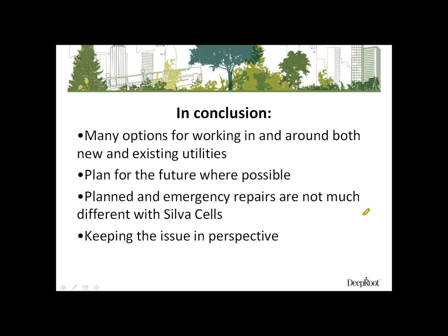If you think of it as a modular block retaining wall, if you have to make a repair underneath that, you have to start at a big V at the top and work your way down more narrow until you get to how wide you want to be, so you have to unstack those blocks. That's not the case with the Silva Cells. You're able to go in there and remove individual stacks of cells without disturbing the integrity of the surrounding ones. So I just want to make sure I got that out there.